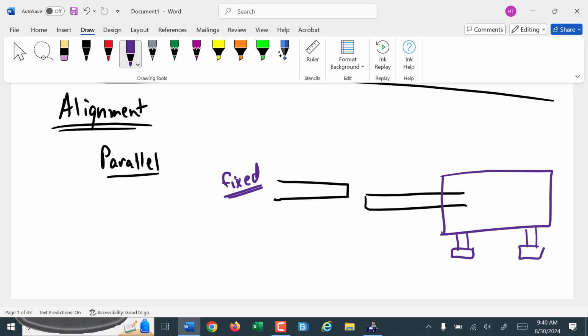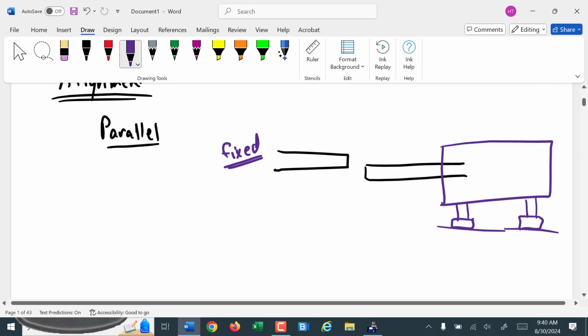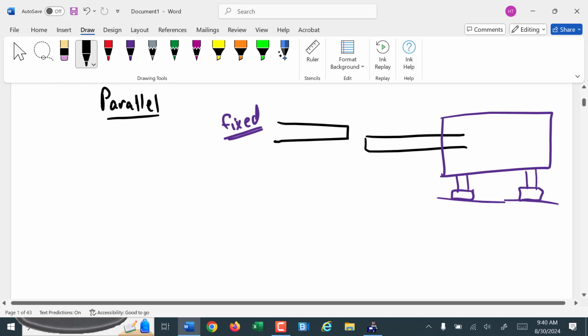The shaft that's on your machine is usually fixed because your machine is usually the larger component. So you're raising the motor to match it. If you have an adjustable motor mount, you either have an adjustable mount where you can raise it with turning the bolts, or you have to shim it.